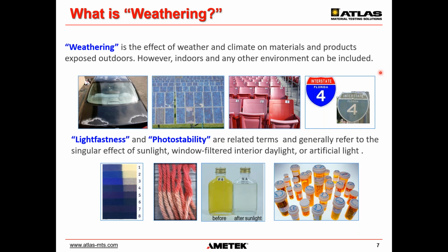When we talk about light fastness, photostability testing, sometimes just called irradiation testing, then we typically focus on mostly the light, but generally we have relative humidity present, we have temperature effects, but no liquid water. And that testing is typically done for interior materials where we don't have liquid water, we don't have rain. So typically textiles, interior furniture, wallpapers, food and beverages, pharmaceuticals are typically tested for an interior climate. So typically photostability or light fastness testing, no liquid water.